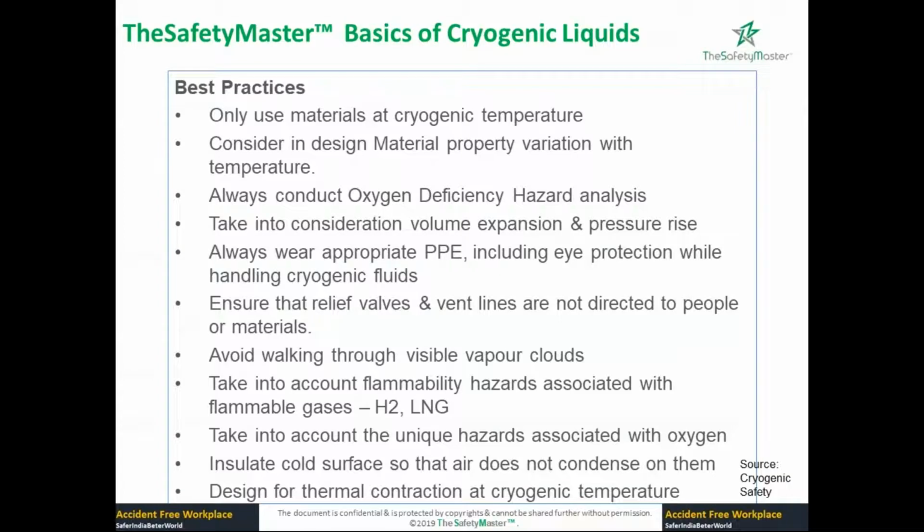And avoid walking through visible vapor clouds. This is one of the issues. When we were young, we did not know it, so we used to walk in the vapor cloud. It looks very nice, like some Bollywood scene. But you should know, the moment you walk inside the vapor cloud, you are exposing yourself to an oxygen deficient environment, especially when dealing with nitrogen vapor or carbon dioxide vapor.